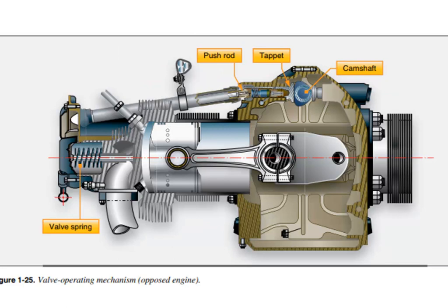Here's a cutaway looking from the front of the engine at the valve operating mechanism. And I just said everything's geared together so that the valves open and shut just where they should in each revolution. Actually, the valves only need to open every other revolution because it's a four-stroke cycle. The four strokes are intake, compression, power, and exhaust.